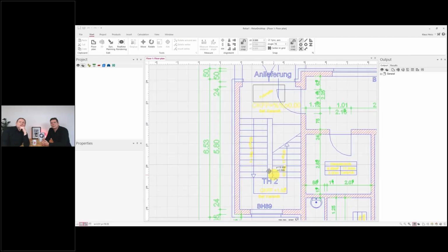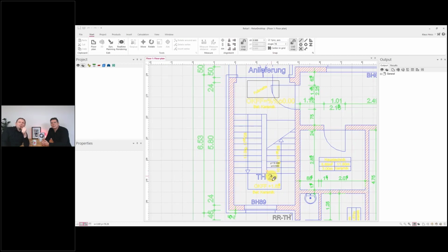These staircases are really nice for the designers, for the planners, because here we have a repeating sequence of steps. It's symmetrical. It's really nice for us. It doesn't trouble us with different sizes of steps or different counts of steps. The steps are the same on all the floors, and the first thing we have to understand is how to interpret the ground floor. The arrows here, by the way, show the direction upward. The arrow always means above.